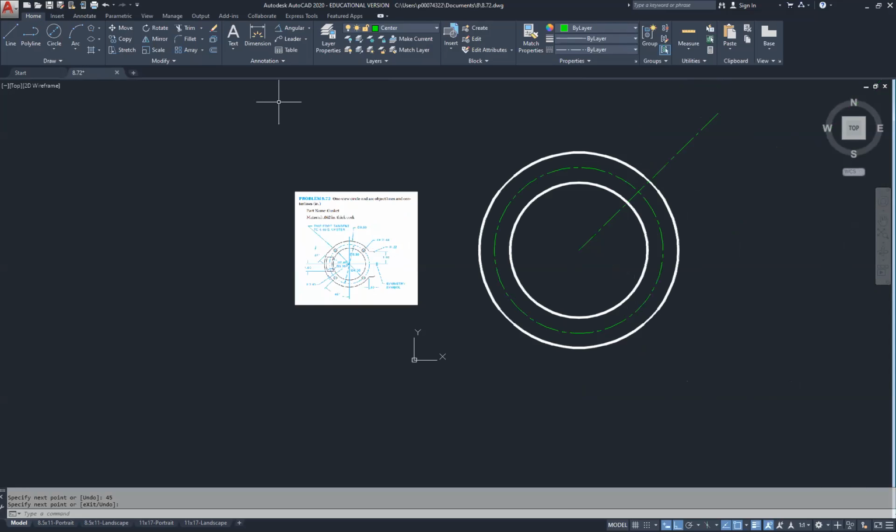Okay. I'm going to go ahead and use the mirror command, selecting this object right here and mirroring it by selecting the base point and then moving straight up, making sure I have ortho on. And then it's asking if I want to delete the source object. The default should be no. In my case, I'll just leave it at default and hit enter. If you do not have no, make sure you type in either N or no, or select down here the no. So we want to keep these two objects.